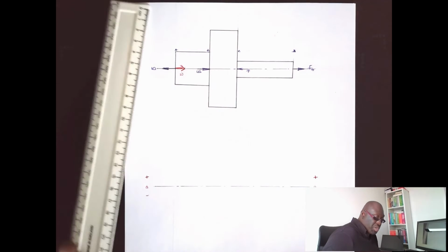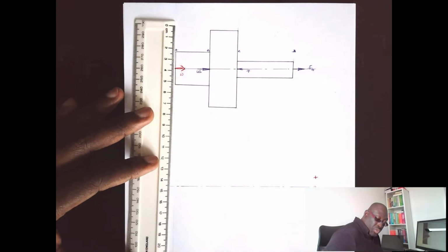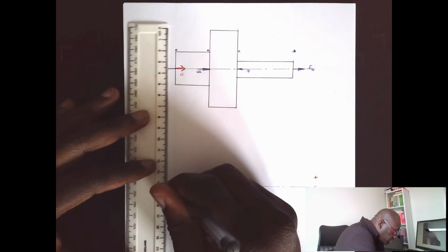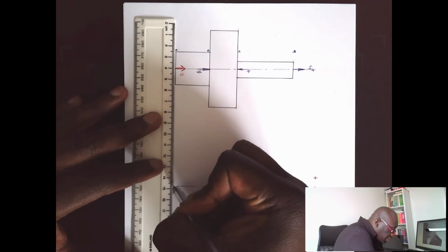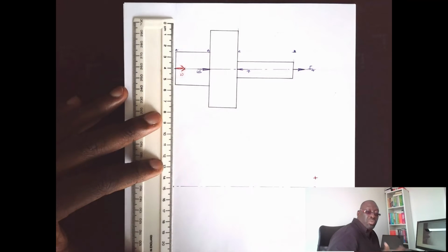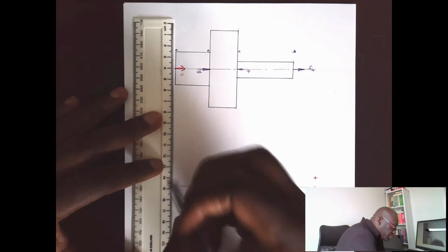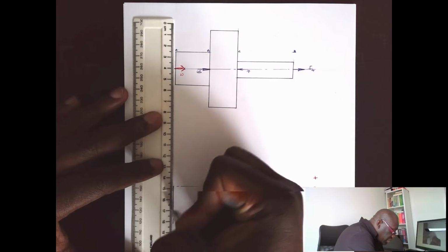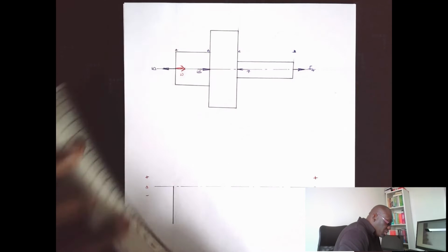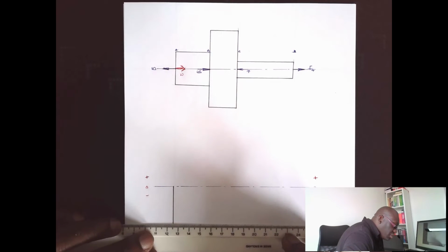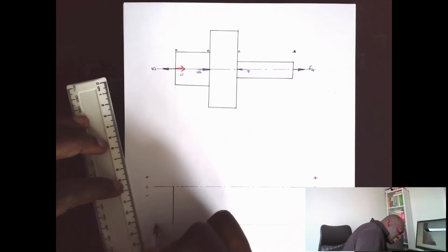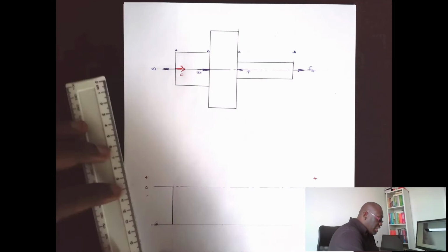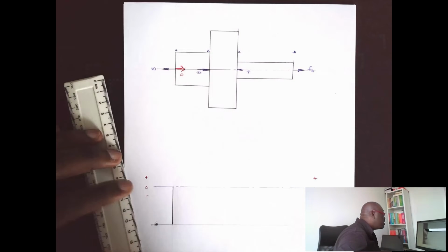So for the load diagram, since the force is going to be compressive, what we will do is draw a line projected from the zero line downwards. And again, if you're going to do this graphically, it might be worth using a reasonable scale. So that would be 10 kilonewtons. Okay, so we can write 10 there, minus 10, so that below the line is negative, above the line is positive.